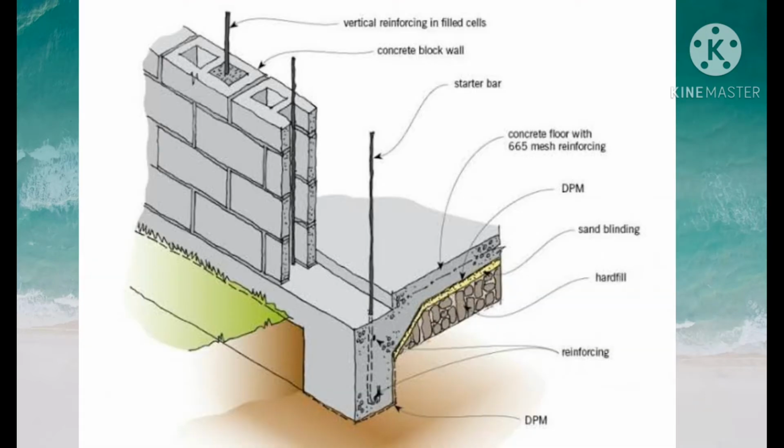For the purpose of brick walls, there are a number of construction options. The first one is the Flemish bond with steel bars and concrete in the voids. The next one is the stretcher bonded wide cavity with reinforced steel bars coated for corrosion protection. And lastly is the solid wall of perforated bricks with continuous voids containing grouted steel reinforcement bars.